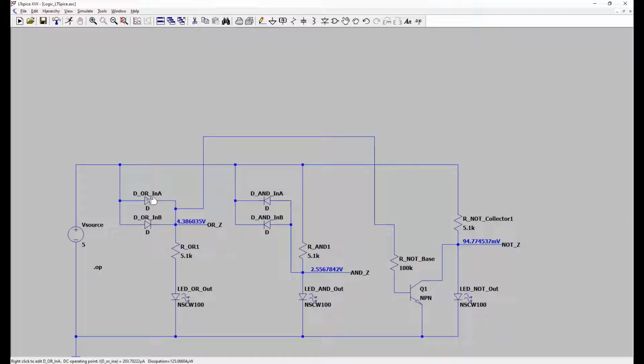Now the big question is, if I chop that and bring it low, the output of the OR gate has gone low with a 37 microvolt output, which of course is not going to be able to turn on an NPN transistor, the 0.7 volt drop requirement here, and we go high.